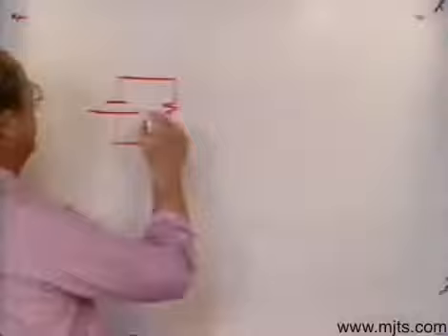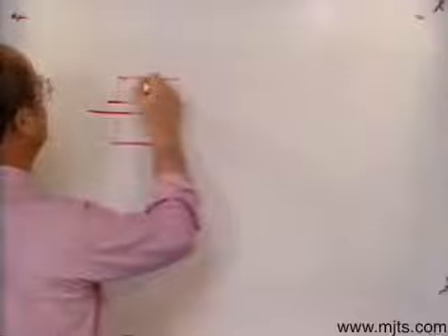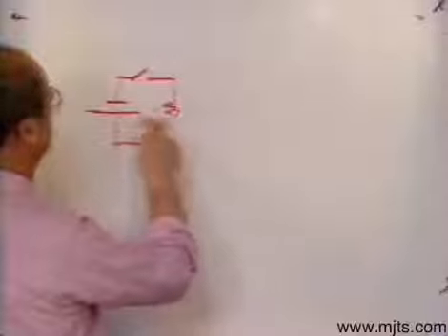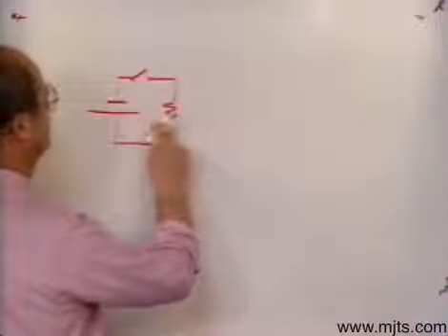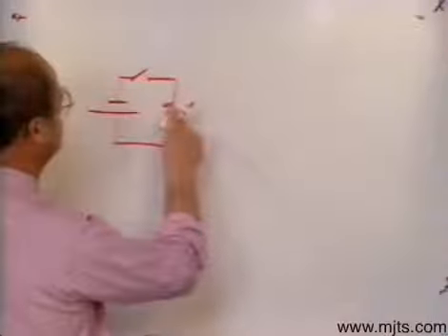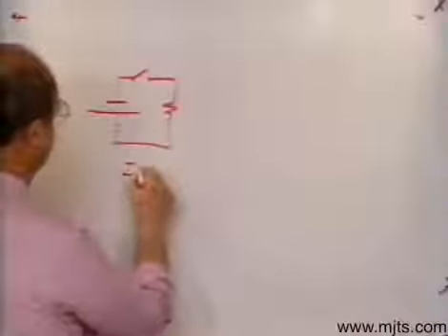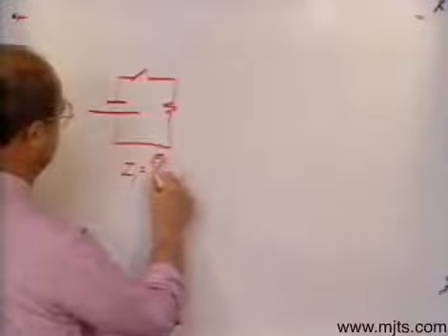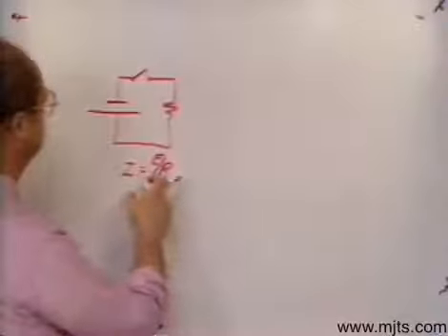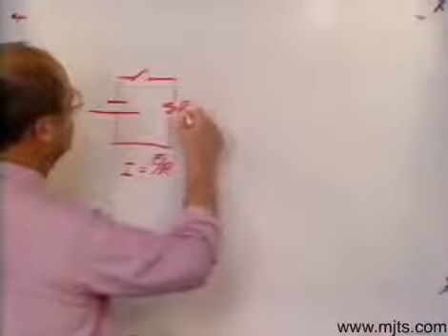Now, if I was to energize that circuit, if I had a switch in here and I would close that switch, the amount of current flow that I would have flowing through that circuit would be dependent on the value of my voltage and the value of that resistance. In other words, the current is equal to the voltage divided by the resistance. They're going to be directly proportional, you see. Now, we represent that resistor by the symbol R.